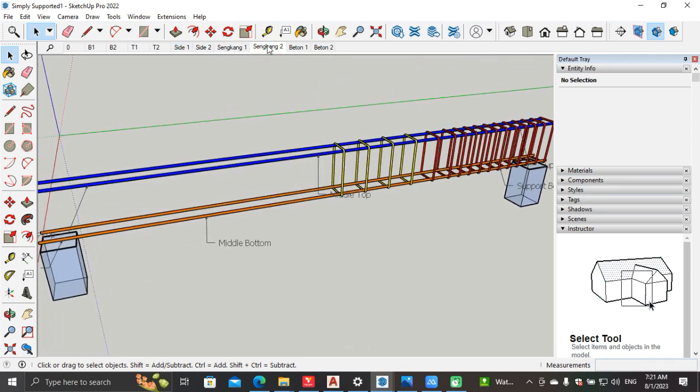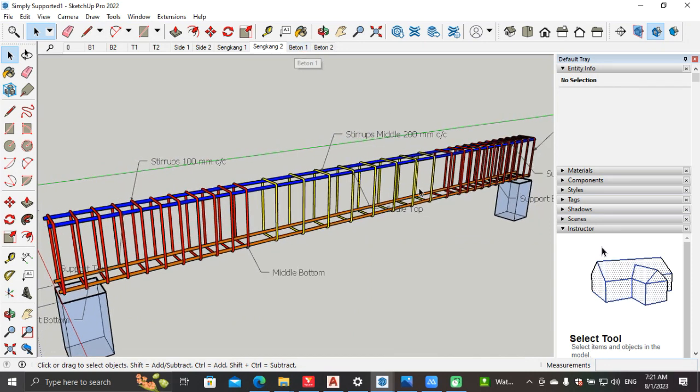And these are the stirrups. Okay, the shear is more towards the support. There you have given the shear reinforcement very much closer, and towards the middle, the shear reinforcement is having some gaps. Okay, so this is the case of a simply supported beam.